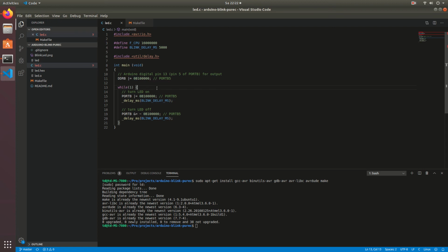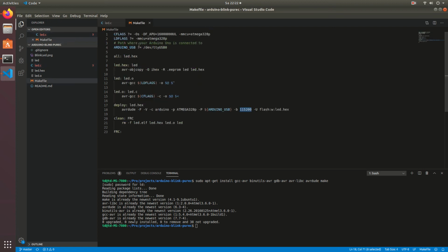So, and when you want to compile that, I've prepared a simple makefile. And here you see the GNU compiler, the AVR GCC compiler, and it's taking a couple of flags. And it basically takes the LED.c program and converts it into an LED.o object file. And then this LED object file is again compiled to an LED file, and that is then with objcopy copied into Intel hex format that can be used by AVRDUDE to transfer it to the microcontroller. And so when we do that here, we just say make.